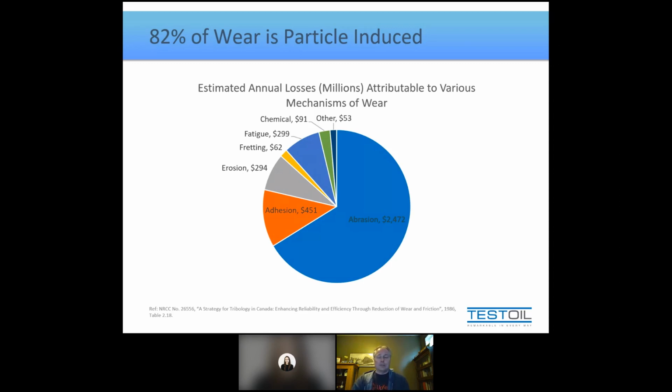It just goes to show no matter how many different ways we've studied this, we know particulate or contamination leads to shortened equipment life. We also know that it's the clearance size particles within that contamination levels that are going to give us the most grief. So we need a way of identifying and therefore excluding or removing these particles if we want the maximum life for our components. Now, on that note, just a quick commentary here.